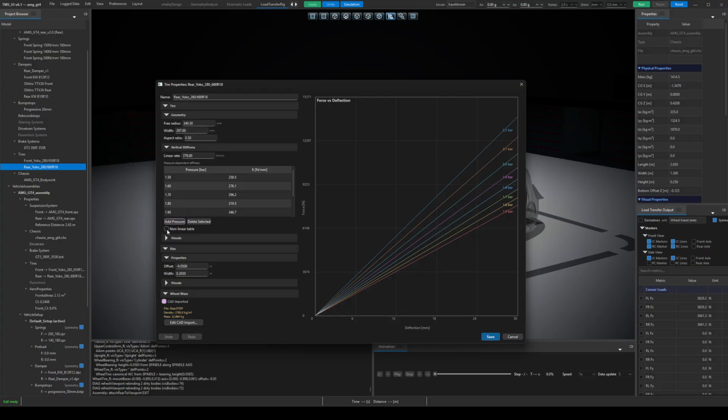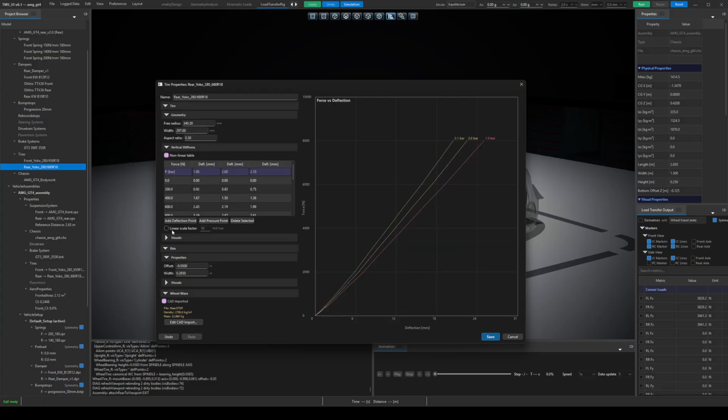A dynamic multi-body model is the closest practical modeling approach we have for this type of mechanical system. It is still a model, of course, so it will never be perfect. But it captures much more of the real system behavior than simplified static calculations. For suspension geometry design, I personally do not know another tool that allows this kind of quick study of how geometry affects roll stiffness and tire vertical loads in a proper multi-body context.